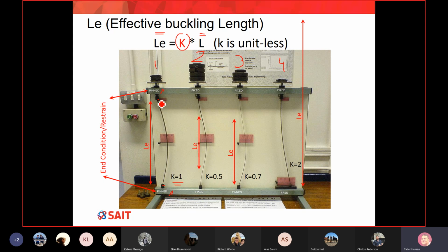Now we've done this in our lab, by the way, in video number 2. In video number 1, we simply add a bracket, where what it does is it simply stops, okay? Look at this. When the column started, it started like a straight line up and then started to curve later on. So that's why in this case, the length of the curve is smaller than the length of the member, where the ratio is 50%. So LE is 50% of L. So K in this case is equal to 0.5 if I fix both ends.